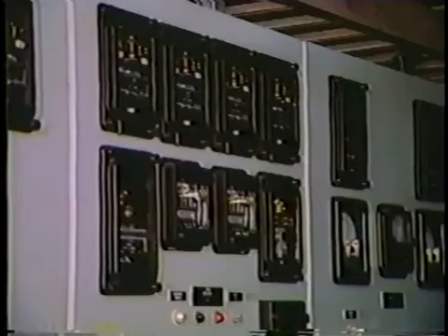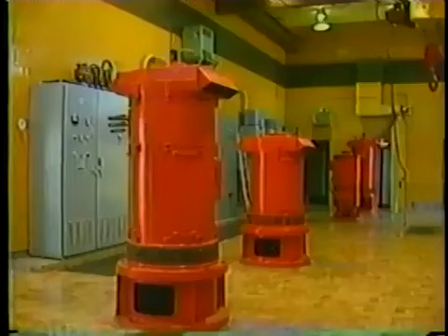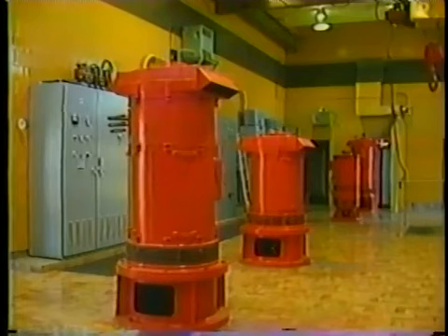Overcurrent relays are widely used throughout the power system, not only for feeder protection, but also for motors in industrial applications and for backup protection in other areas. When applying time overcurrent relays of the electromechanical type, two points that must be considered are overtravel and reset time.